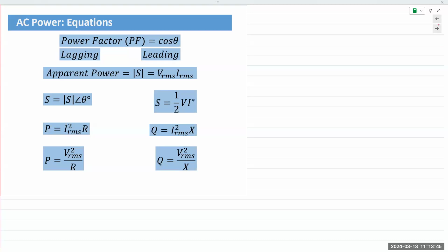Okay, and again, I'm talking about chapter 1. PR, power for a resistor, can be given by the product of the resistor voltage and the resistor current, VR times IR. So if you were given the voltage for a resistor, you could find the current using Ohm's law and then apply this equation. Or if you are given the current for a resistor, you apply Ohm's law, find the voltage, and then still apply this equation. That would be an extra step.